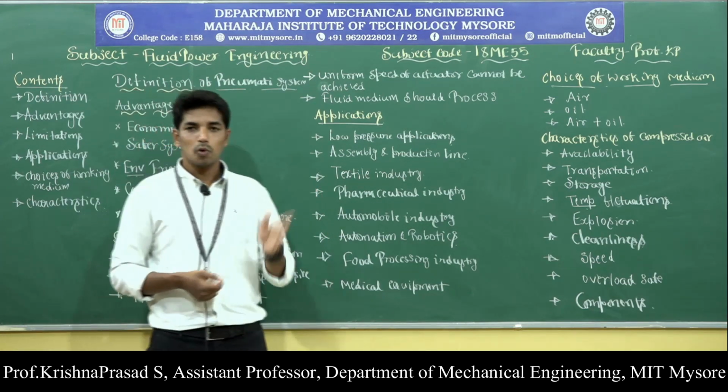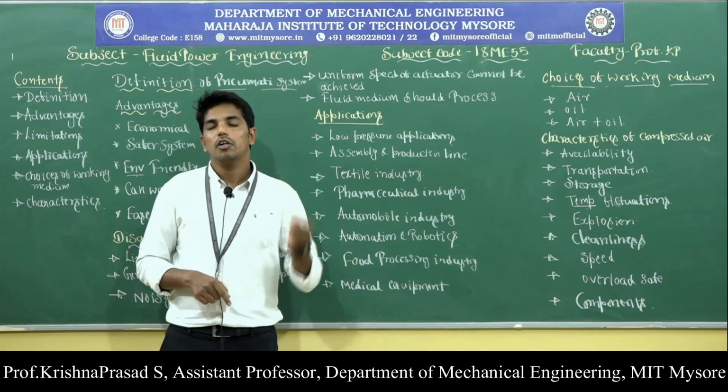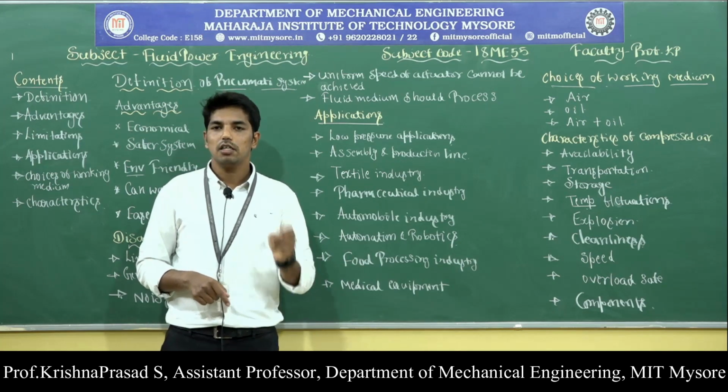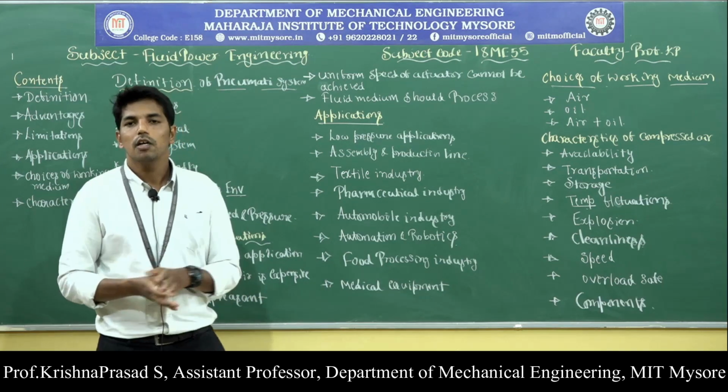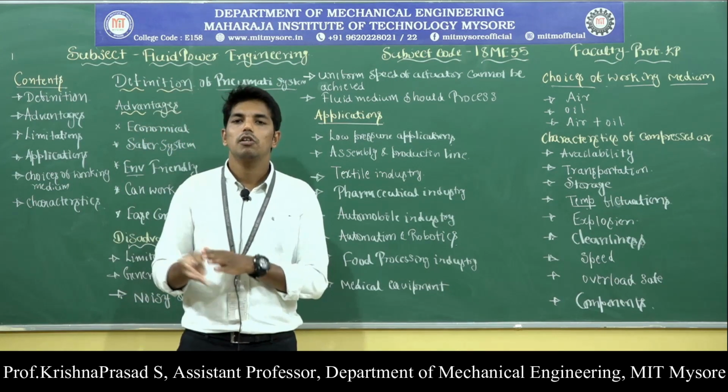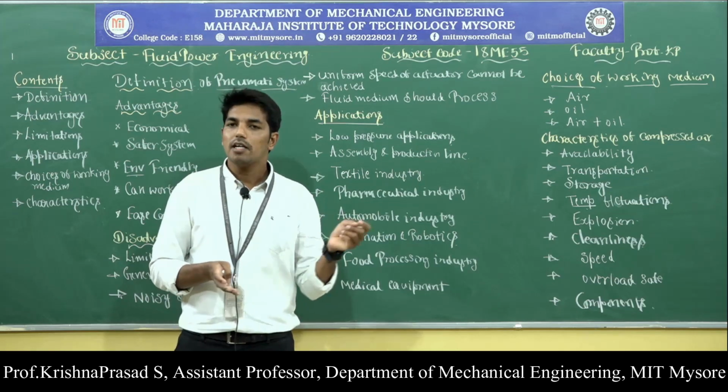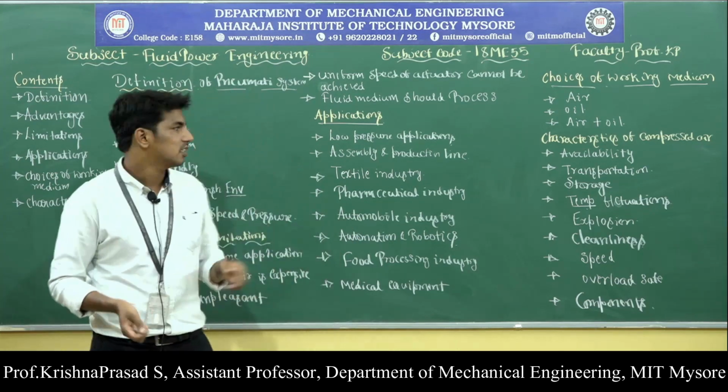Then the fluid medium should be processed before it gets into use, in order to ensure the absence of dust, dirt, as well as water vapor. If these kinds of contaminants are not removed, they will lead to wear and corrosion of the parts of the pneumatic system.